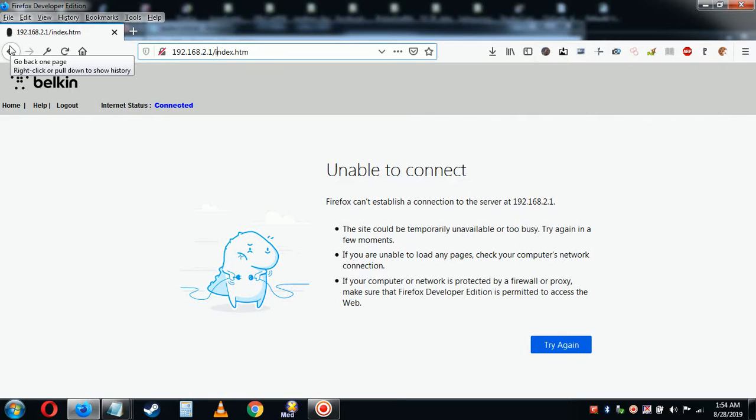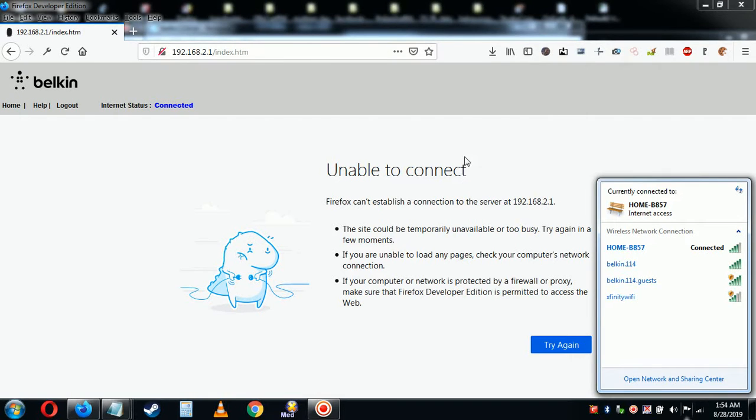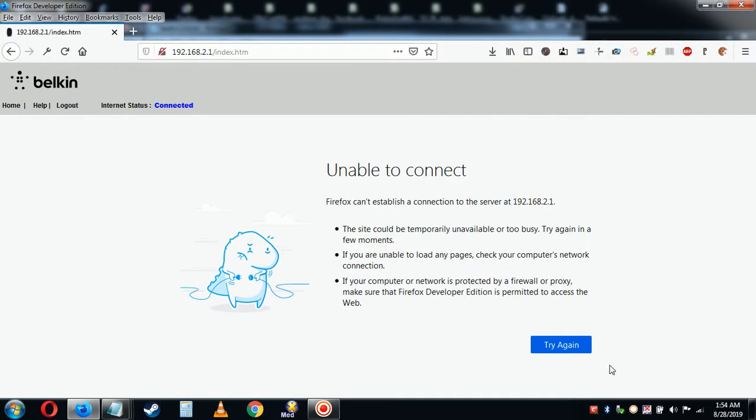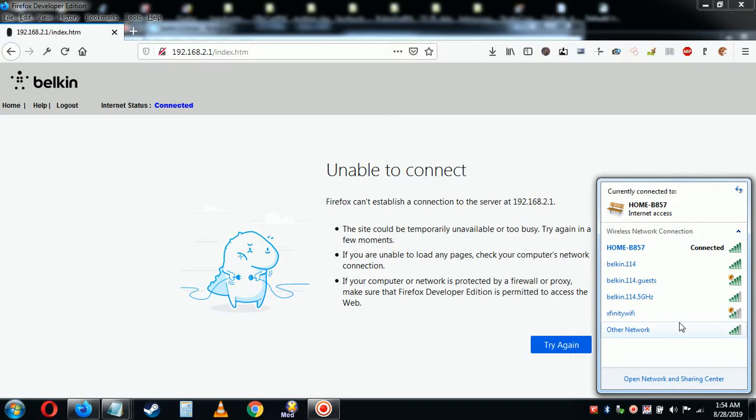Back. It should be rebooting up right now. I just unplugged the power connector and plugged it back in, so that's really all you need to do when it does that, and you need to reinitialize it. It's just as good as hitting the reset button, but quicker actually. Alright, so we're good there.